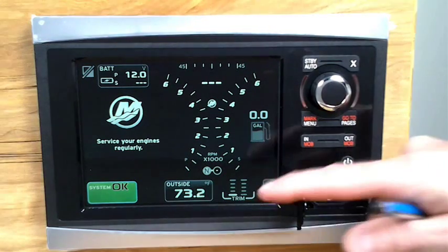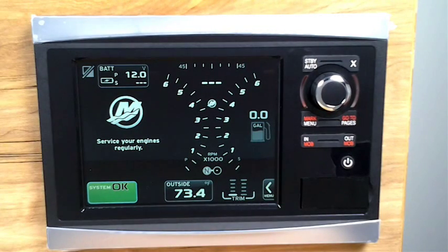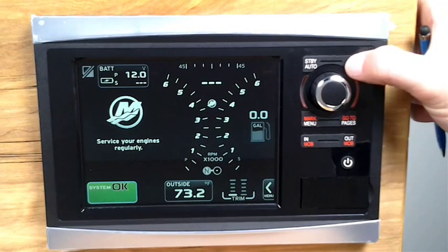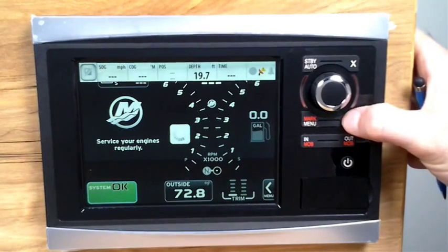It is recommended that you back up the vessel personality onto a micro SD card before changing the configuration settings. The backup allows you the option to easily reset the VesselView back to the current configuration.